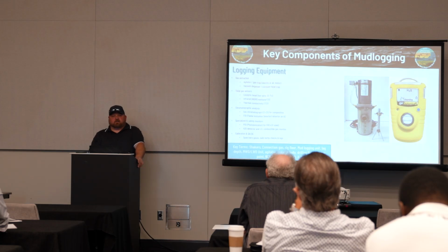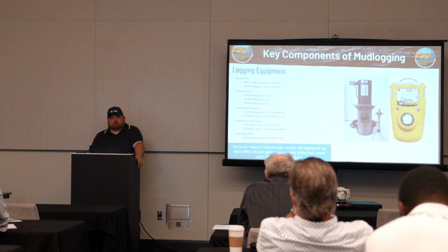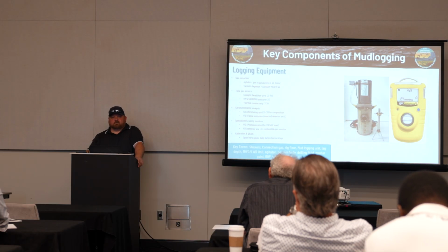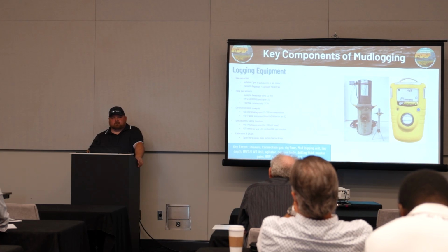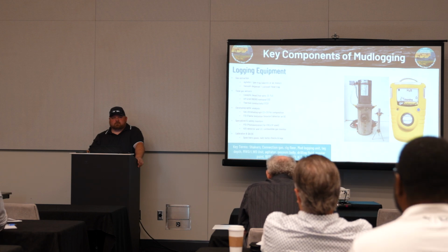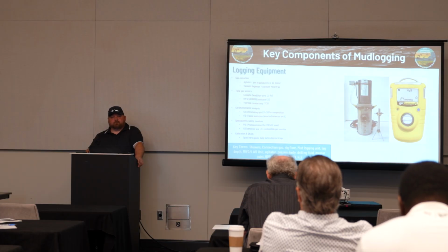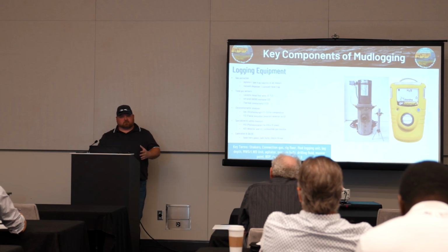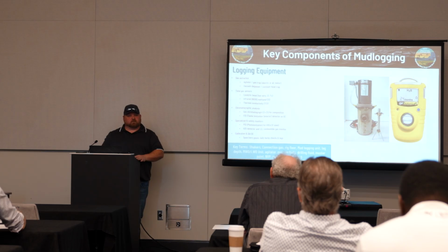So in that case, I'm talking low readings on any gas that you get. A lot of times it's just the actual detection of these low concentration gases in these low pressure reservoirs. In that case, I would prefer an FID because it does read all the way to C7, and so it's more accurate on the heavier side. Even though those gases are gas, they're still liquid, so it'll read those liquids better than an IR system will.